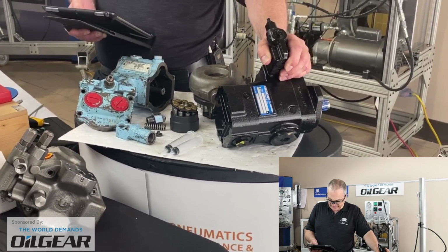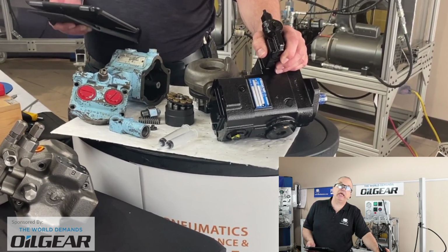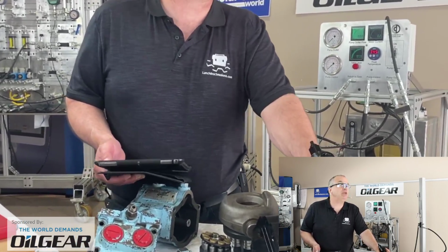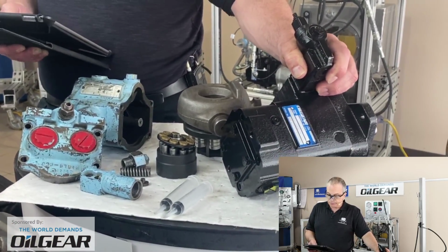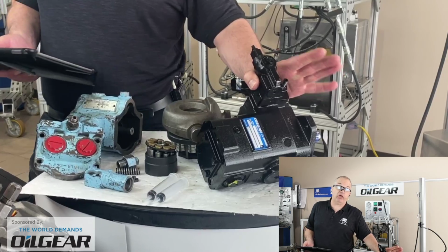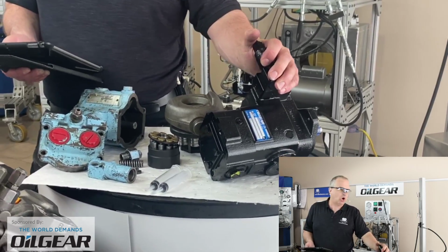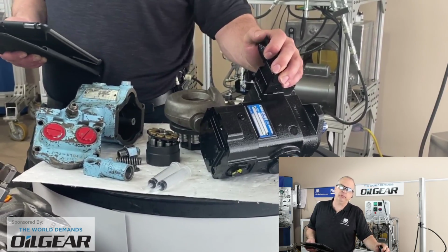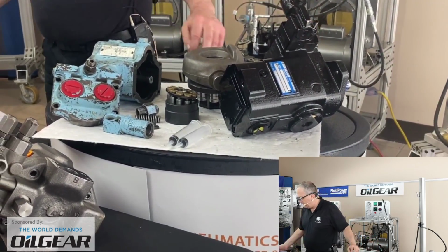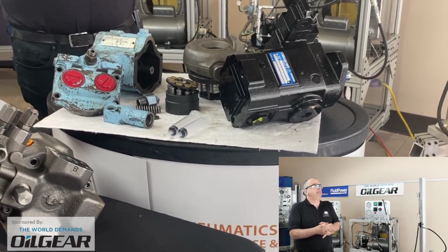Okay, be very careful with that and understand what maintenance and adjustments are required. In most cases that relief valve is there to protect from fast pressure spikes that can occur in the system, and is the faster acting device compared to the pressure compensator. So I am by no means ever encouraging anyone to remove the relief valve from a system with a pressure compensated pump as an experiment. Always go back to an engineering group for your system before changing anything. All right, we'll move on. There are a few more questions that came in late, but for now we'll move on, and perhaps I'll come back to those a little bit later.